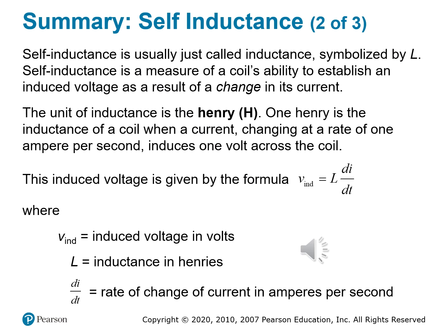Self-inductance, usually just called inductance, is the property of a coil to oppose changes in its own current. It's not about interaction with other coils, that's mutual inductance. This is a coil resisting itself. The unit of inductance is called the Henry, and we symbolize that with the letter H. And here's a definition. A coil has an inductance of 1 Henry if a current that changes at 1 ampere per second induces a voltage of 1 volt across the coil.